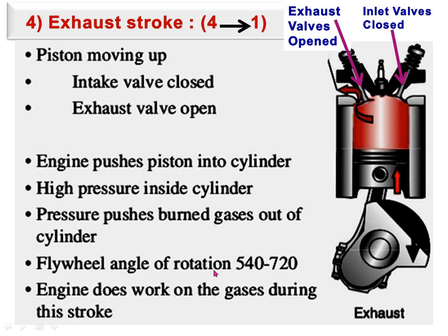Flywheel angle of rotation is 540 degrees to 720 degrees, meaning a further 180 degrees of rotation of the flywheel in the exhaust stroke. Engine does not work on the gas during this stroke. During this stroke, the engine is not working on the gases.